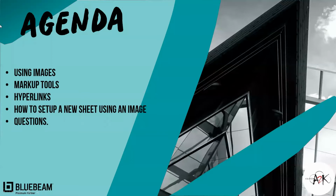Just a bit of a rough agenda. I'm going to focus this one on using images in Bluebeam. A lot of companies don't do it so much. It's great to do for facade work, which I'll be doing today, and like rectification. And if you have an image in, how you can actually start to get dimensions off an image. So it's a great feature. If you are using it for dimensions, obviously the most straight on you can get, or the most perpendicular view, is the best for getting those images out and measuring up accurately.